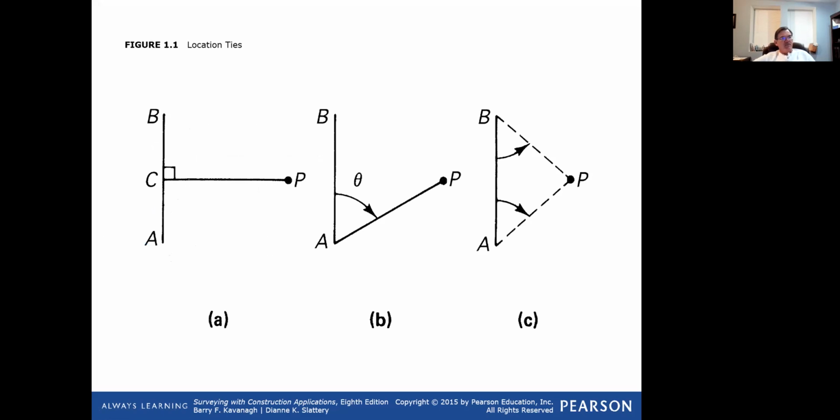We had multiple people holding a tape, and we would use trigonometry and check this distance to get the hypotenuse of a triangle. Remember, a squared plus b squared is equal to c squared, so the square root of a squared plus b squared gives c. That's what we would use to check this distance after we came down, went 90 degrees, and put this in.